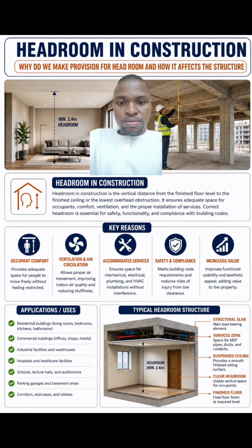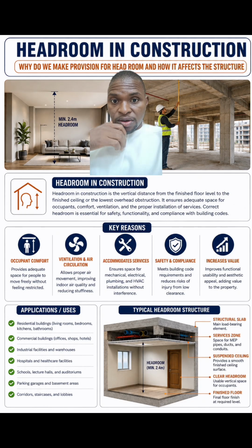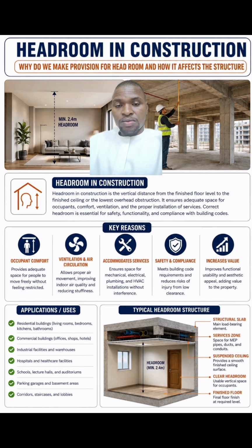So we'll be taking a look at the typical headroom structure. From your slab, which is the main load-bearing element, we then have the services zone. Below your slab is the services zone, where your mechanical, electrical, and HVAC components, space for MEP, pipes, ducts, and conduits are placed.